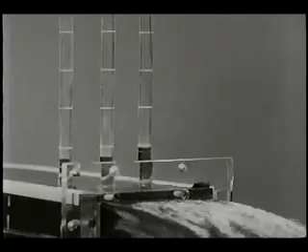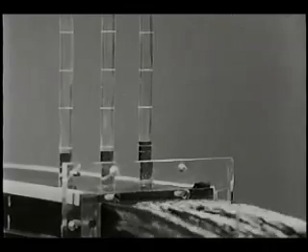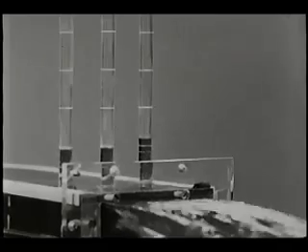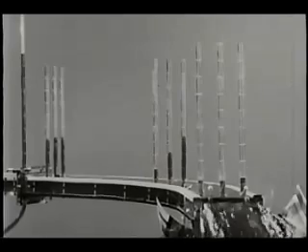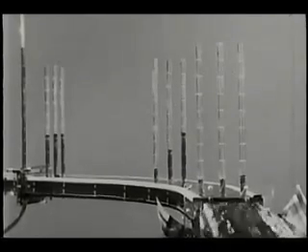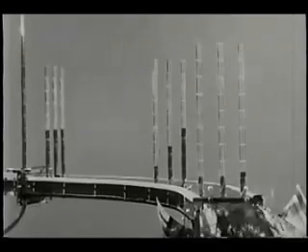As we increase the flow, all the pressure differences also increase, according to the square of the velocity. But the pressure difference due to curvature remains a constant fraction of the dynamic pressure. Another example of streamline curvature is the throat of this half venturi.